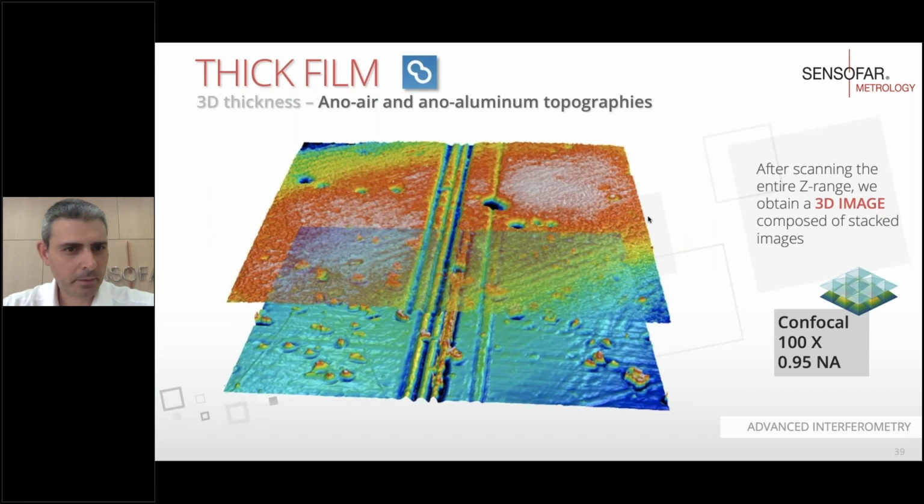That is an example of an anodized aluminum layer with no dye components on it. This is about 7 microns total thickness, and you can see that because of this previous explanation, you are able to retrieve the three-dimensional topography of both the top air-to-layer interface and the layer-to-substrate interface. To get those three-dimensional measurements, we were using a 100x 0.95 numerical aperture objective.